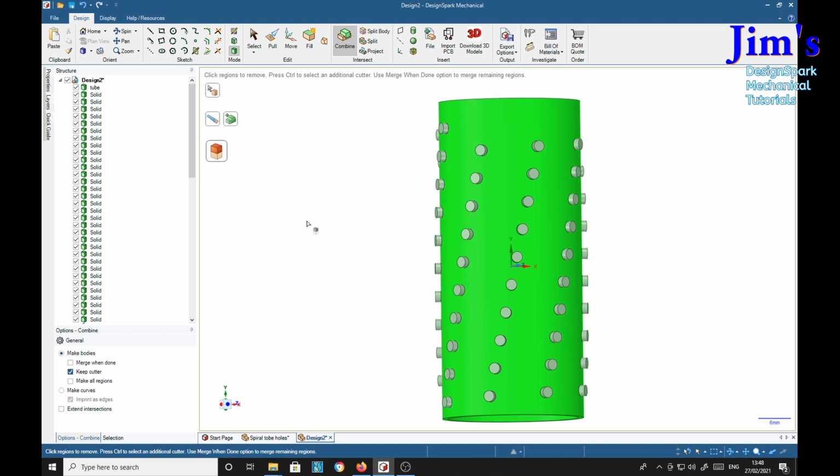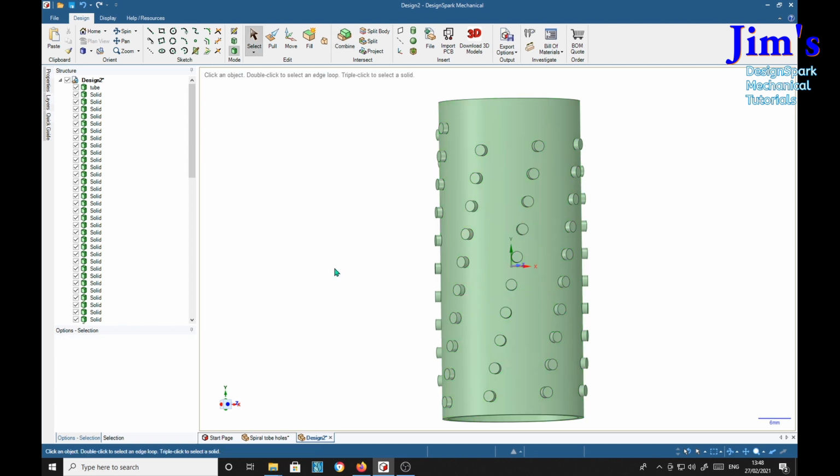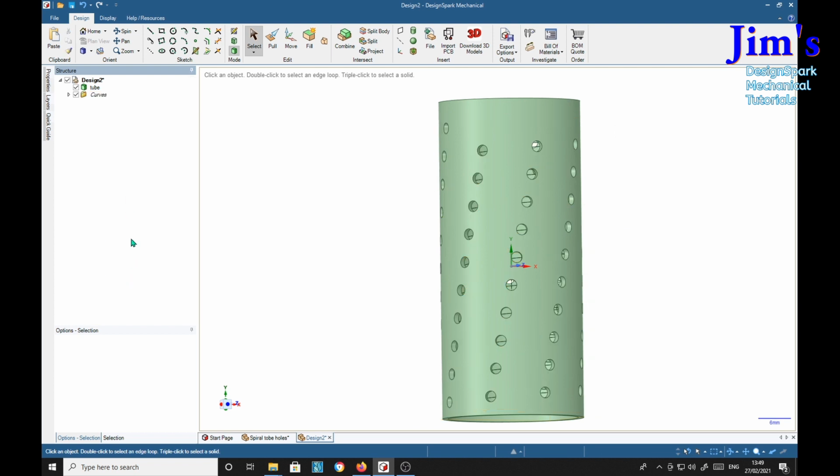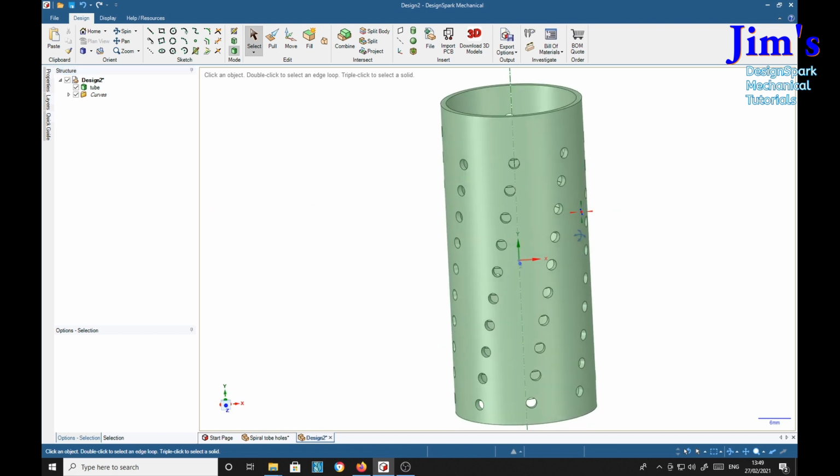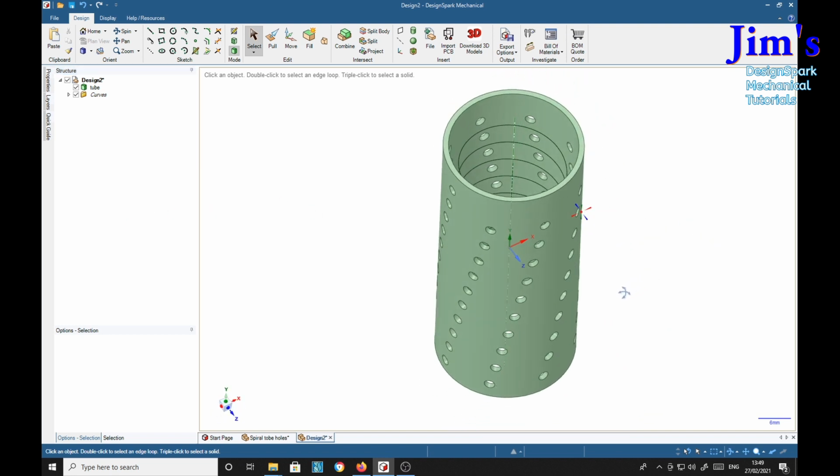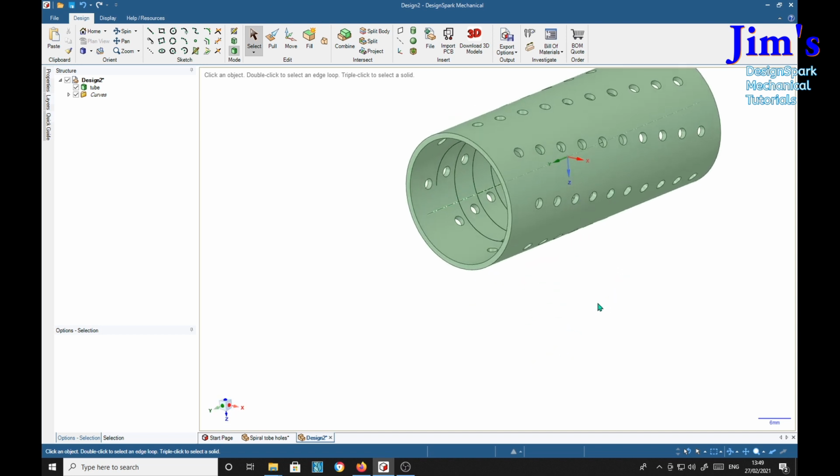So we'll see we've got a cursor that we don't want. So just escape key and move and it goes away. Go down to the bottom. We want to select everything from pattern right to the top, so hold the shift key. I want to keep the tube, select everything there, and then hit the delete key. There we go.